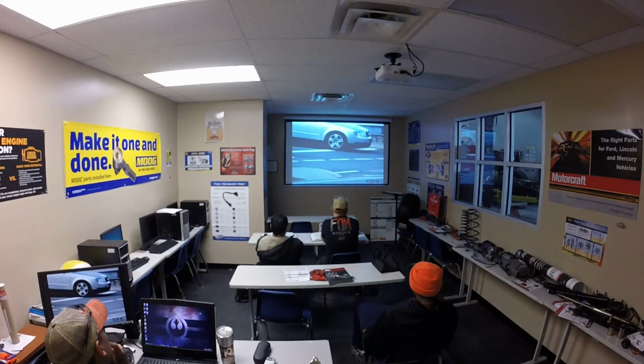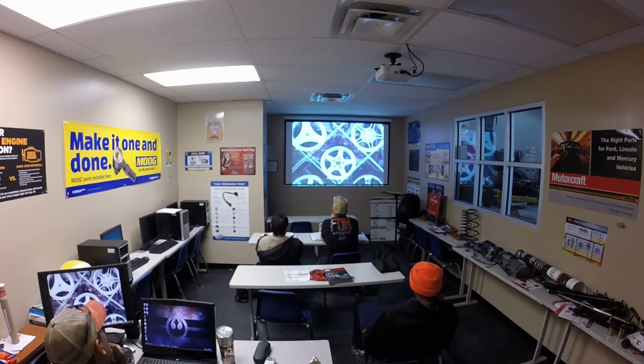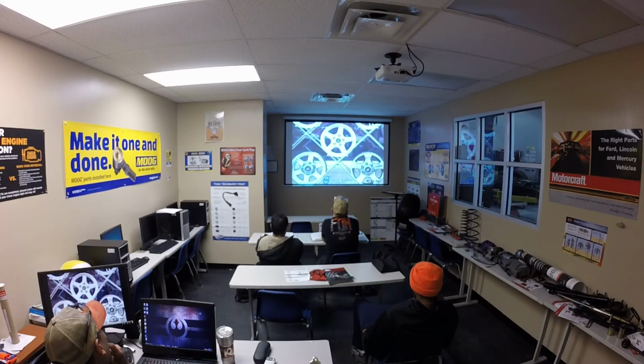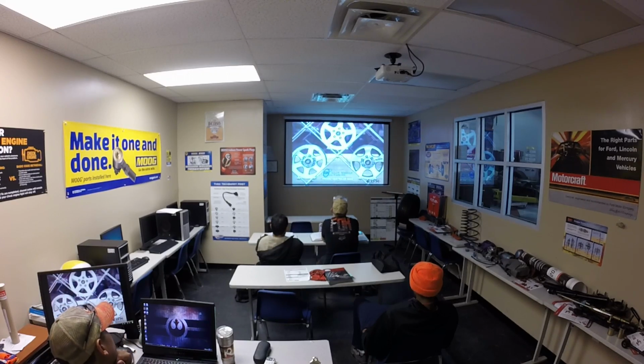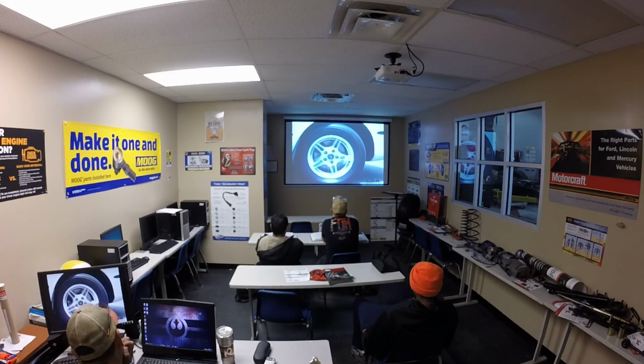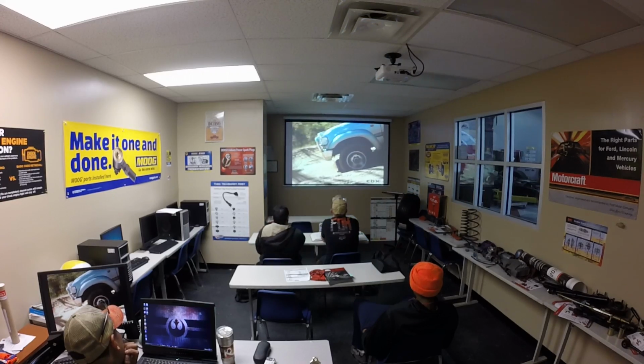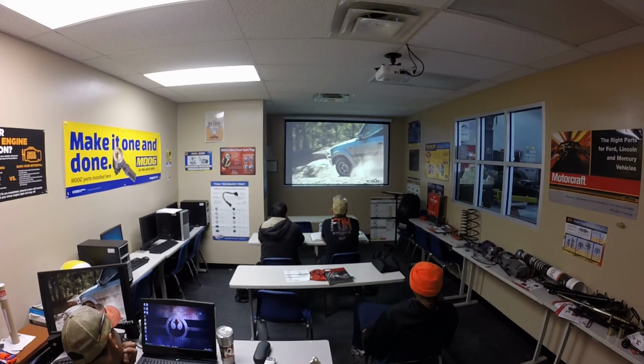Wheels can also be made from cast aluminum alloy. Alloy wheels are popular because of their appearance and because they are lighter than similar steel wheels. Aluminum is a better conductor of heat, so alloy wheels can dissipate heat from brakes and tires more effectively than steel ones. These are often called mag or magnesium wheels, but wheels made of magnesium are rarely used on road vehicles. Most wheels have ventilation holes in the flange, so air can circulate to the brakes.